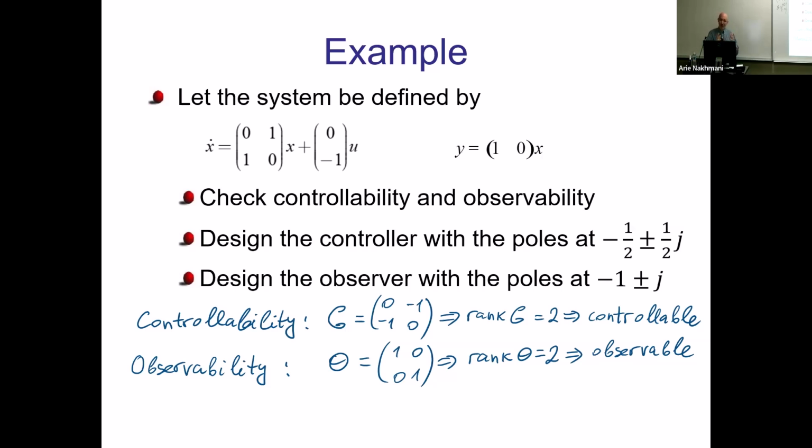If the system is not observable, sometimes you still can design observer, but you'll have the same issue as with controllers, which means if the pole which was canceled for the non-observable pole is stable, it still will converge, but you cannot control how fast it will converge because you will not be able to move it from its place. Okay, so it will converge as fast as it can based on its location in open loop, right? But in other cases, you can control all of the locations of all of the poles for the controller.